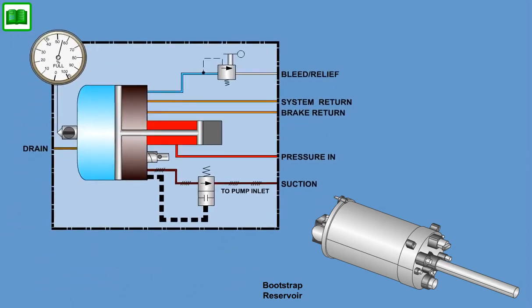The reservoir provides the necessary fluid volume demanded by the hydraulic system, including pressurization of the pump inlet. Changes in fluid volume due to thermal expansion and contraction, system leakage, and differential area of the user actuators have been taken into account in sizing the volume of each reservoir.